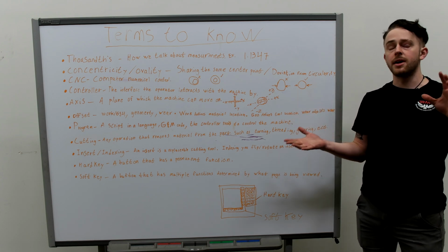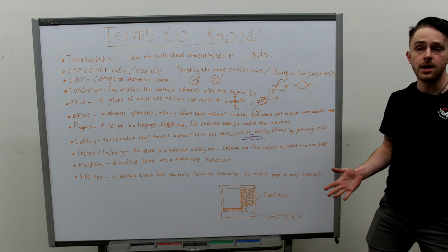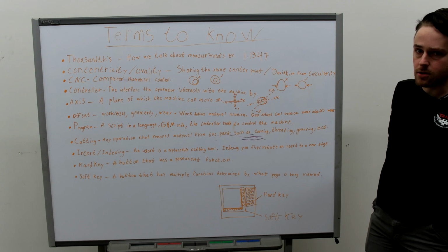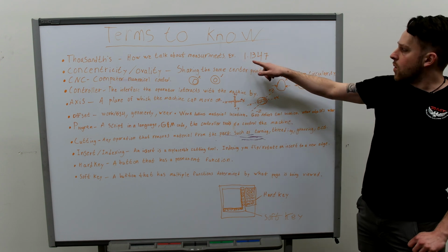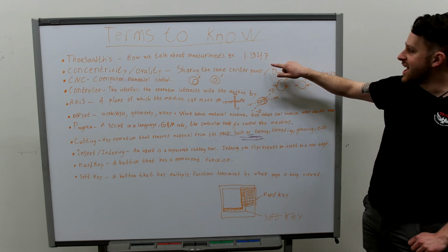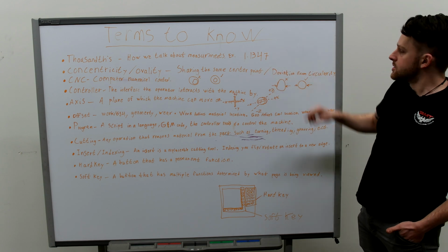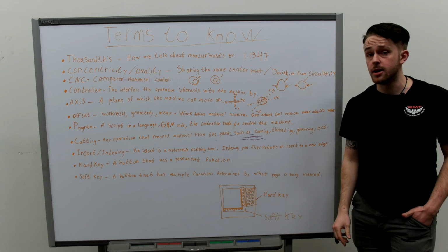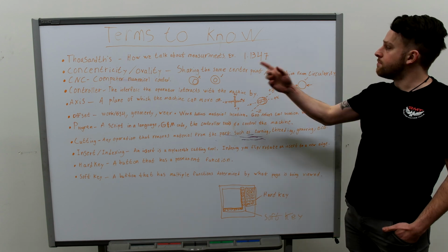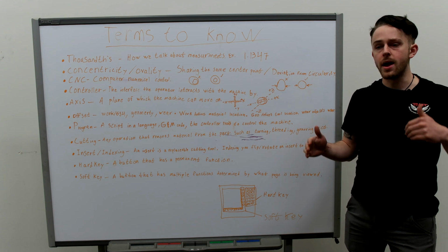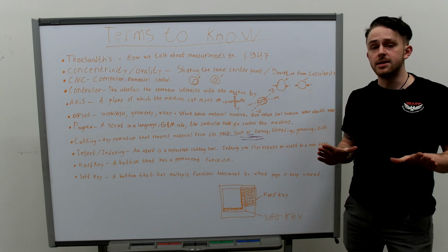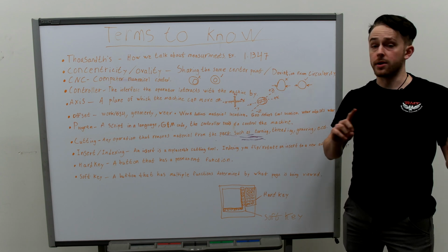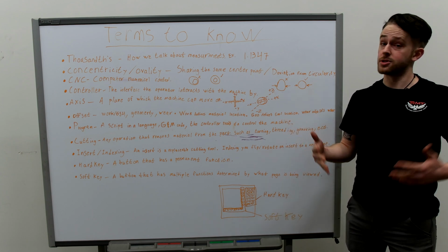This is something very commonly used in the machining world. And so right here I have an example that I wanted to go over. So we would read this 1 inch, 134 thousandths, and 7 tenths. So typically we won't be working with tenths as that is an extremely small measurement. But it's important to have a standardized way of saying this, because if we don't, then there can be miscommunications amongst operators or engineers, and we could have parts cut very incorrectly.